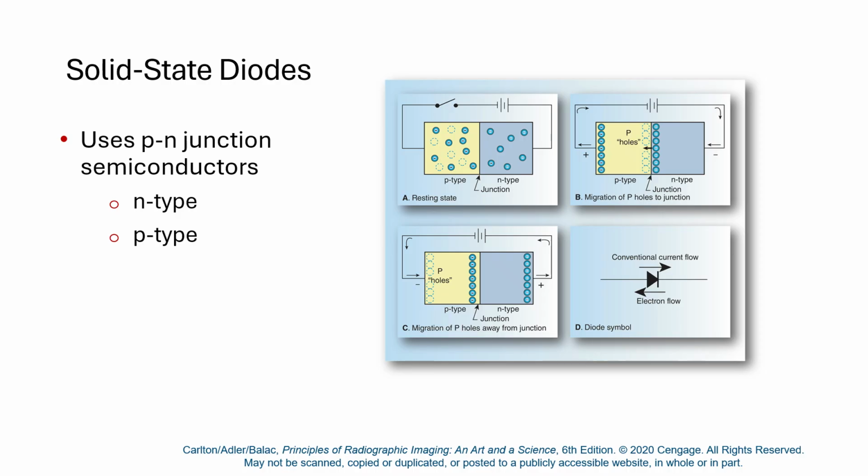If we add a dopant like phosphorus or arsenic, though, then we get N-type doping. N-type doping means that there's an extra valence electron in the material, more than silicon. Silicon has 4 valence electrons. Okay, and so in N-type doping, you create an abundance of charges that can be motivated to move. In P-type doping, you create vacancies in the valence of the molecules in the material that electrons can jump into.